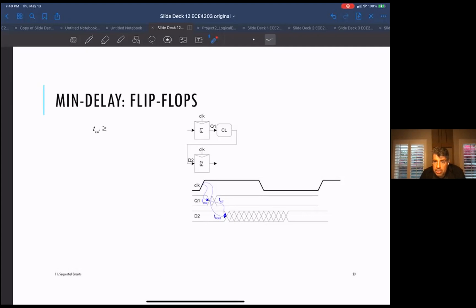It's not good because you won't meet your clock frequency specification, but at least you can get a working chip by making your clock longer. At least you can debug your chip, if nothing else. Maybe you can negotiate with your customer to buy your chip as it is, maybe give them a discount. I don't know.